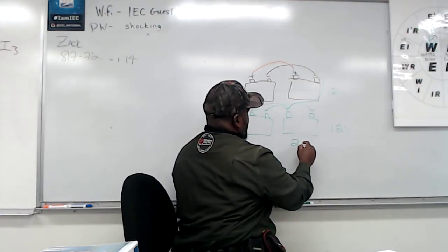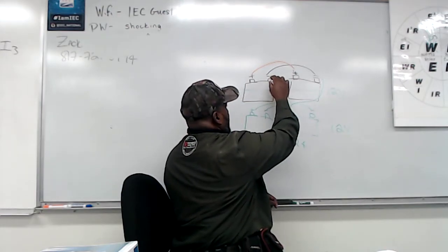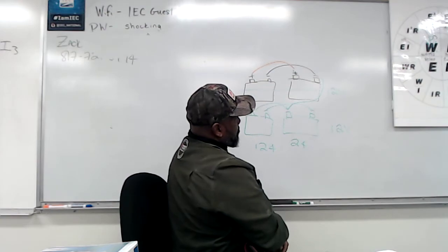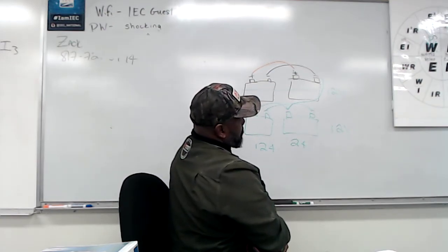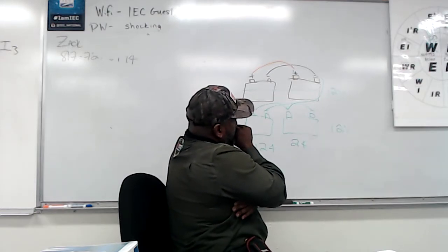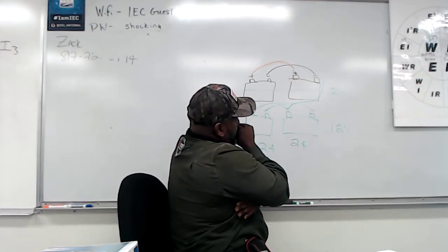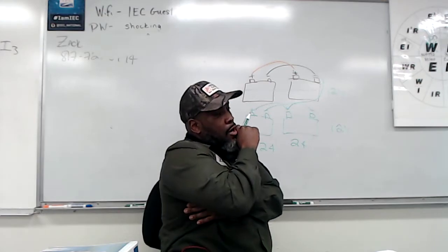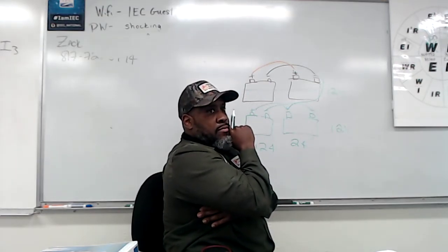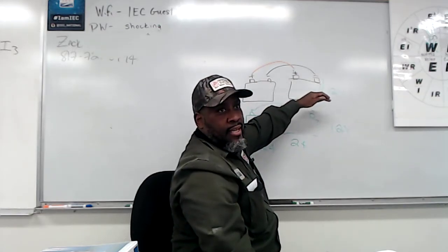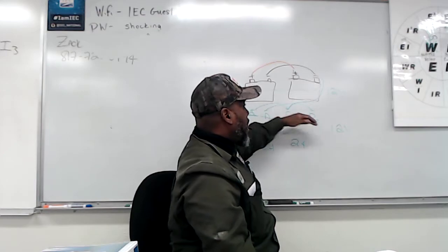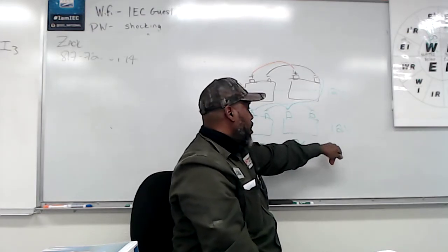Okay. And the same thing over here, right? Yes, sir. Are you adding all those together, because you got 4 batteries that are each giving 12? No, because in a parallel circuit, voltage doesn't change. So I need how many volts? 24. I get 24. So this parallel set is in series with this parallel set, which gives me 24.